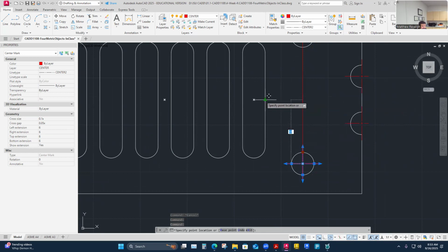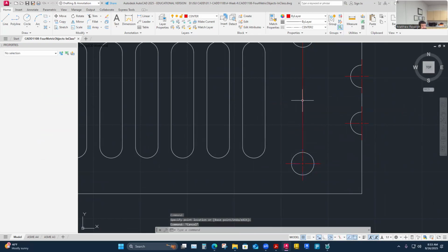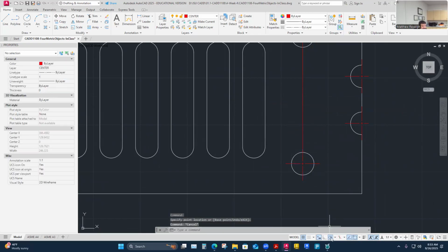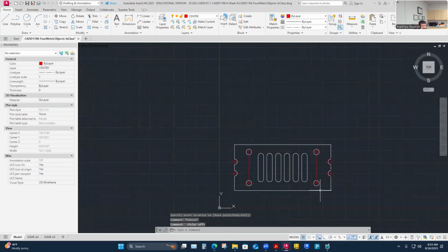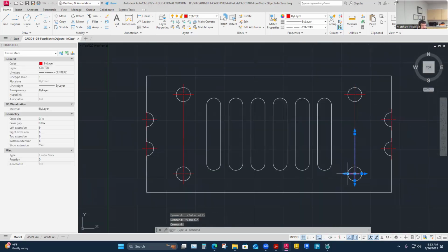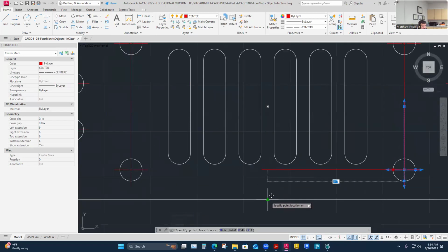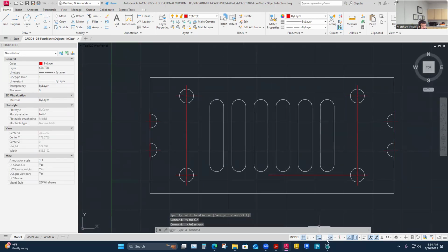I could even reference this over here, but you look for that snap tracking to show up. If that's not showing up, it's because your snap tracking is not on. This one here, if I unclick this, I don't think I'll get that. So let me try it now. Yeah, see, I can reference that. Oh no, I still will. It's another one, maybe. This one, maybe? Yeah, snap.